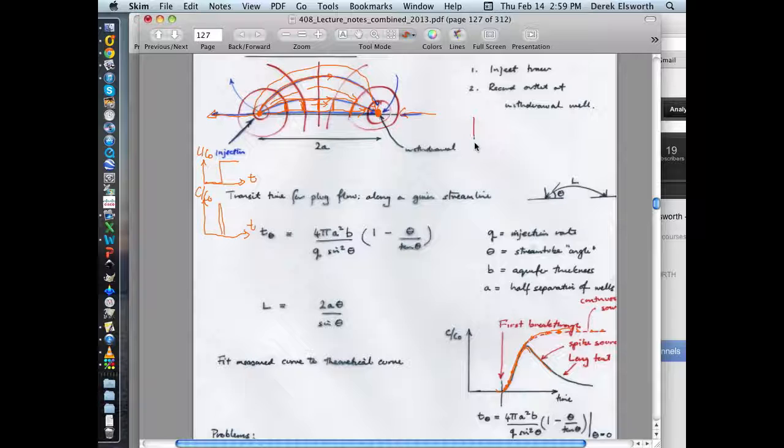And so it's kind of like the case if you look at our idea of dispersion, that you have this front going through here with these fingers attached to it. And this is C0 back here, and this is concentration equals 0 ahead of this. These, of course, are flowing along fast paths, and they arrive early, and they do something to this behavior. But this hasn't happened because of anything to do with the natural process of this occurring in the aquifer. It's happened purely as a function of the geometry of the flow regime.